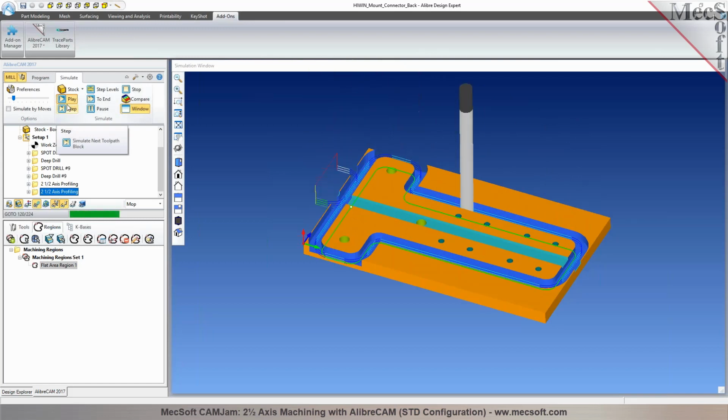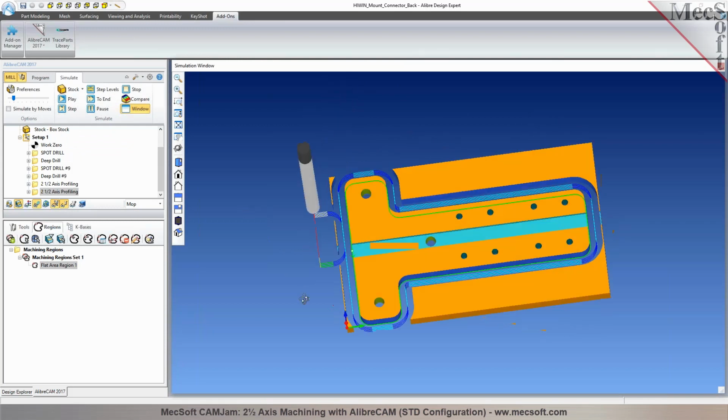There's a couple of ways we can do it. One is automatic bridges and tabs, where it automatically places those bridges and tabs, or you can even precisely control where you like the tabs to be placed in the part. So in this particular case, it probably makes more sense to have bridges and tabs like 2 on each side over here, right? Because there's not much material on these areas. So 2 on these 2 sides would help.